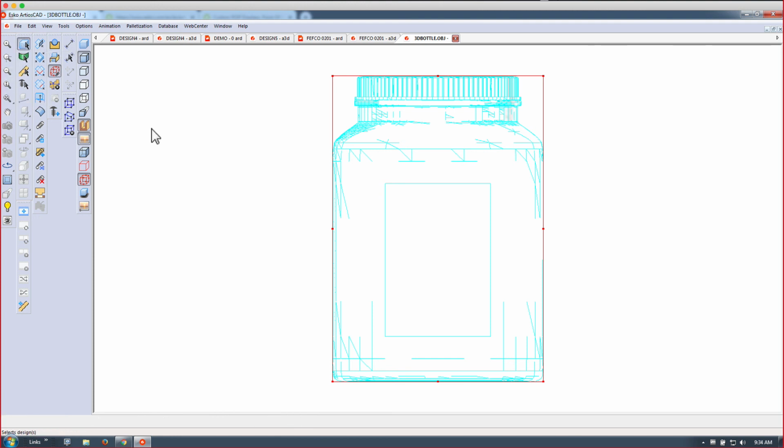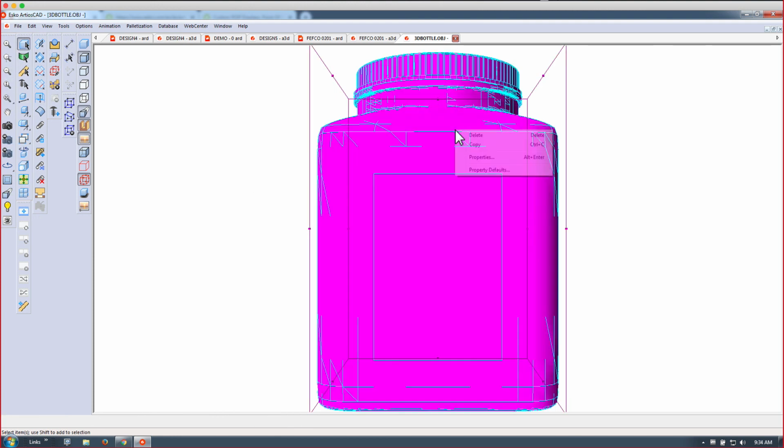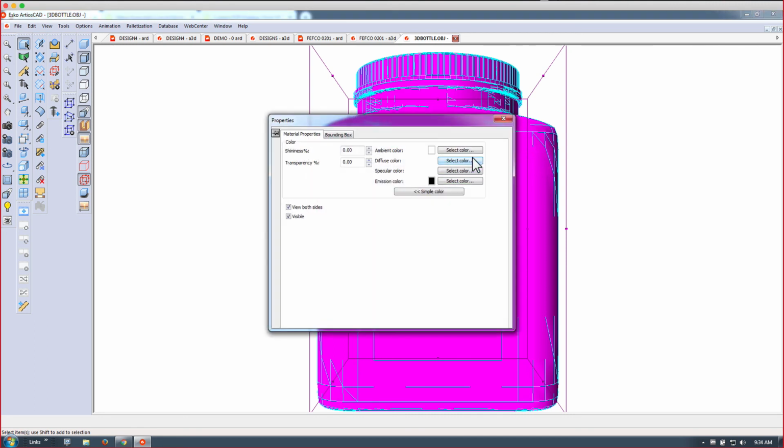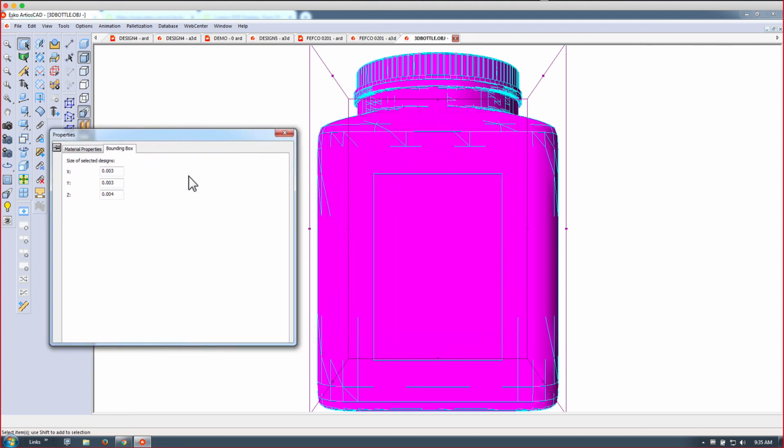One thing you definitely want to do after you bring in this model is first look at the dimensions, because sometimes coming out of these 3D programs, your scaling factor might have been set totally off, right? By a factor of 10, 100, or in my case, by a factor of 1,000. That's where I started seeing that the dimension was so small that my object is actually 3 thousandths of an inch X, Y, and Z.